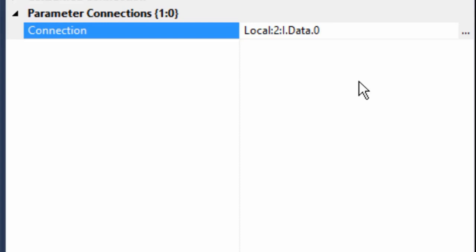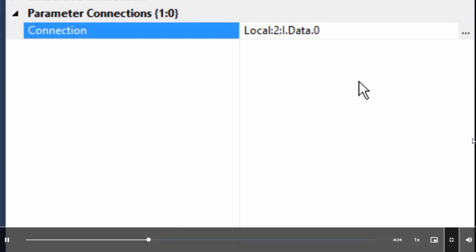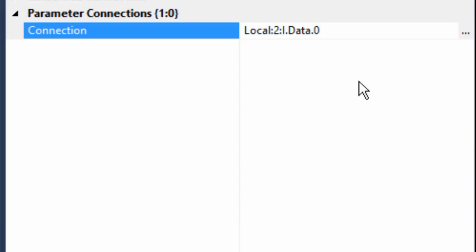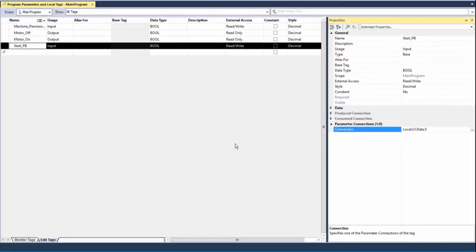This functionality can be quite useful for our customers and only became available with the advent of program parameters in v24. Prior to v24, customers used aliasing to encapsulate their data. With aliasing, we cannot update data synchronous to the program scan without adding additional code that buffers the data. Be aware that there is another program parameter usage called in-out that updates synchronous to the hardware requested packet interval, or RPI. So our customers now have more options and greater control over how their data updates.